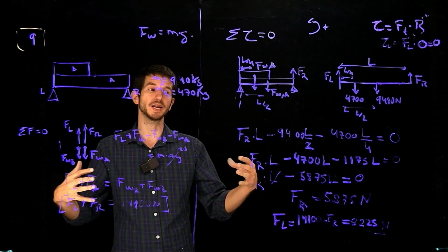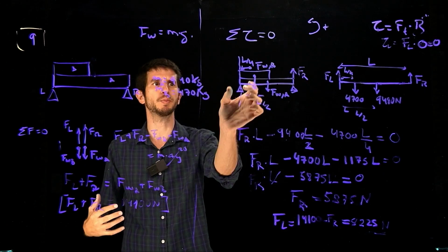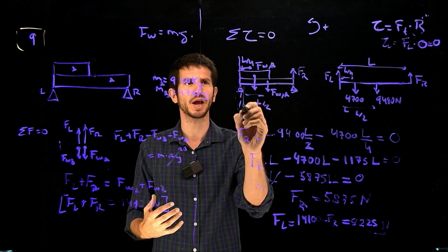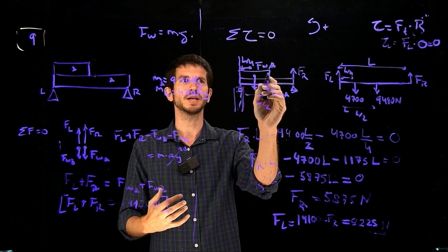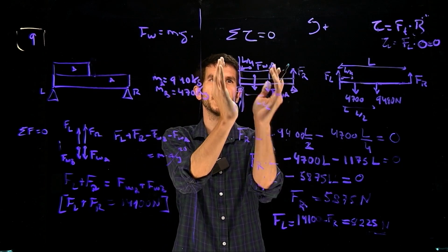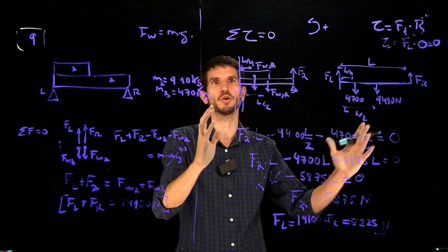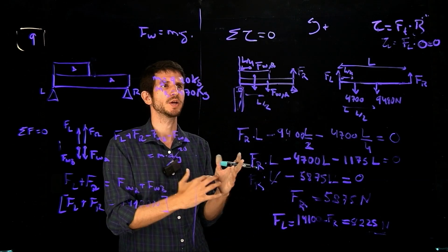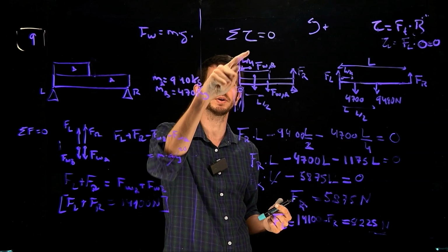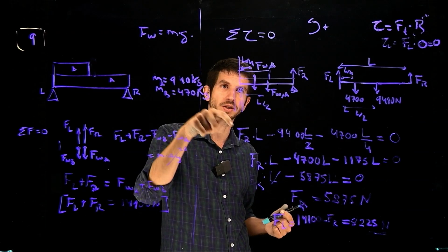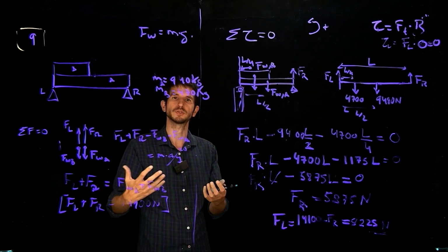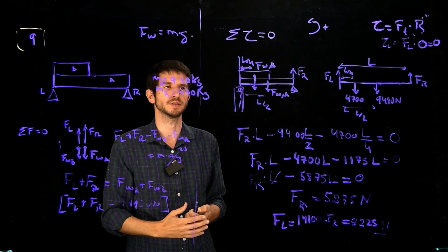And if we were designing something like, for instance, let's say this is a pillar that goes down to the, let's say that this was the roof or whatever, right? And say, can I put, for instance, a swimming pool in here, and I put a load, and my load is applied in that area, only in that area, not the other one. Is this floor going to collapse? Is it or not? So I'm going to find the equilibrium conditions. And then I find how much is the weight or the load on this column, and then I can see, is this column going to have enough strength to hold that or not, and all those things.